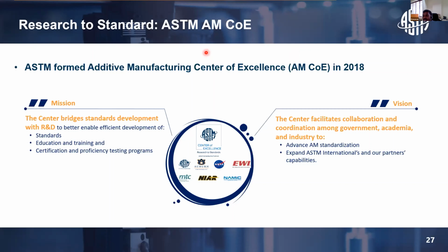Yeah. So next question: how can we integrate AM testing standards, especially for miniature test specimens, into our current conventional testing standards? I think that was the thing I was just mentioning before. Yes, yes. Right now, the creation of that standard has been going on for more than 3 years, because of the many tests we were performing to make sure that the variability between specimens from the conventional E8 and the miniature specimens is acceptable. So a lot of tests are going on right now.